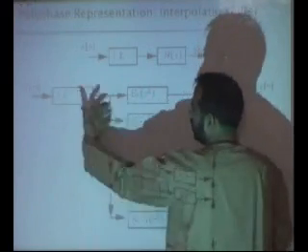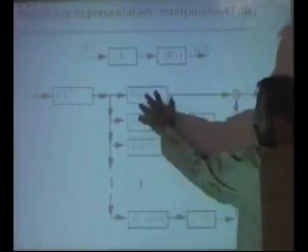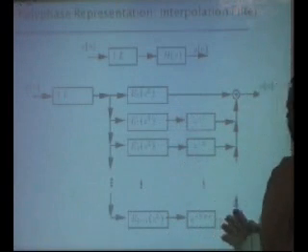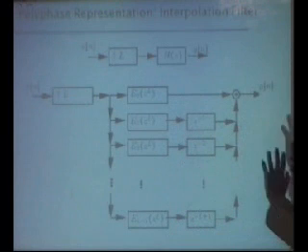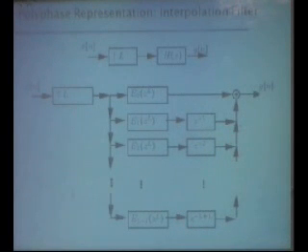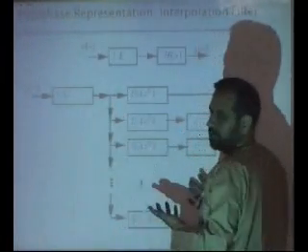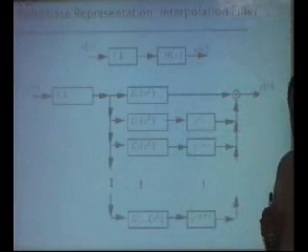So you insert zeros, then feed it to all these filters with zeros in them, then delay them in this fashion, then add them to produce y of n. This is what it says. Again, inserting zeros here or inserting zeros in all the branches are equivalent.